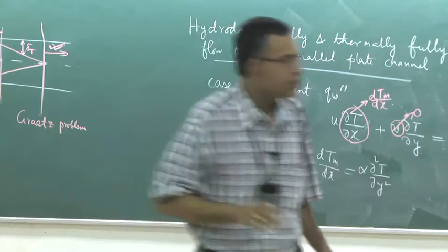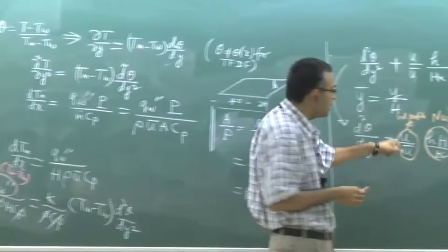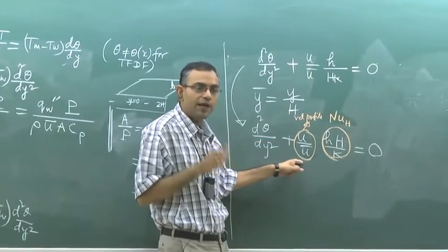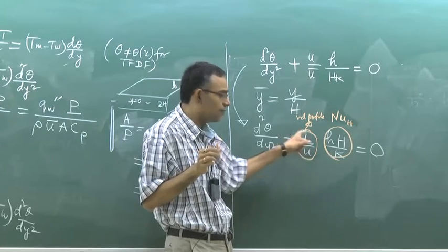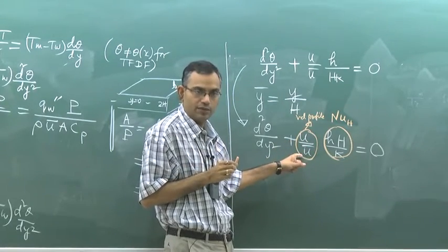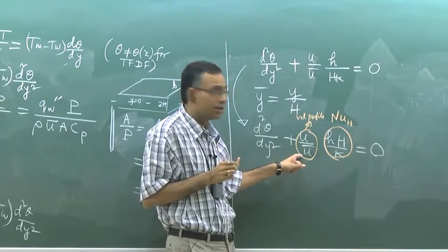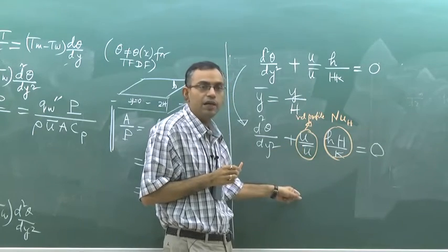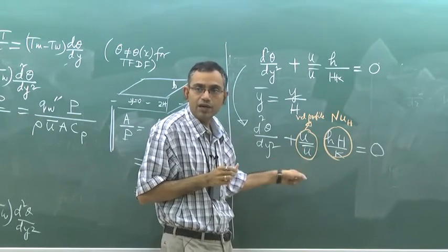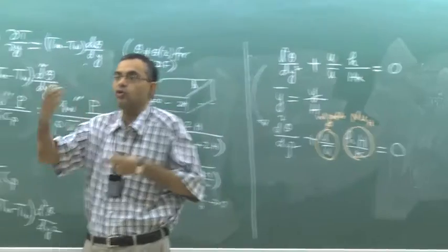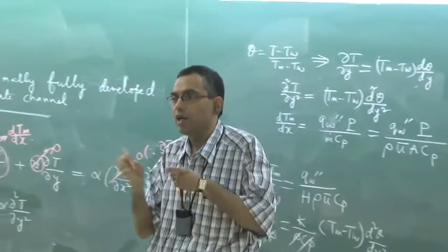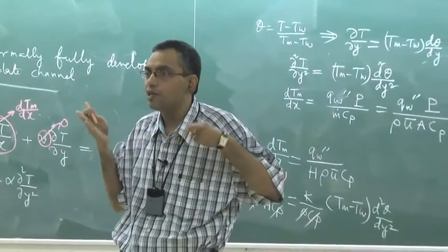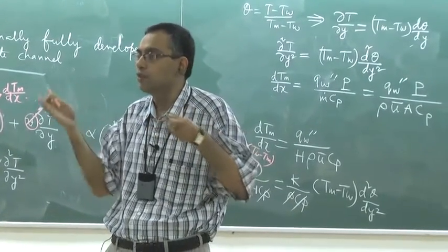1, right. So that is a very special case, very simple algebra to deal with. I am not working it out here, but please take it as a homework and complete it by yourself, that consider a plug flow with u by u average equal to 1. Then complete the remaining derivation. I will do the derivation for a more involved scenario when u by u average is not equal to 1, but it is a fully developed pressure driven flow, that is Poiseuille flow.